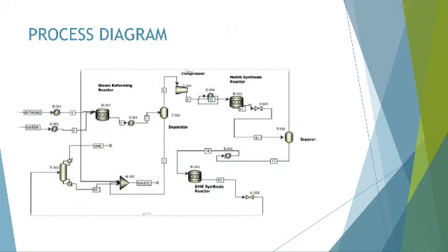In the process diagram, you can see that we have the steam reforming reactor. It's a three-step conversion which starts from the natural gas, which undergoes steam reforming or partial oxidation to create syngas, that's mainly hydrogen and carbon monoxide. This syngas is then catalytically converted into methanol. Finally, we remove water from the methanol through a dehydration reaction to form DME.